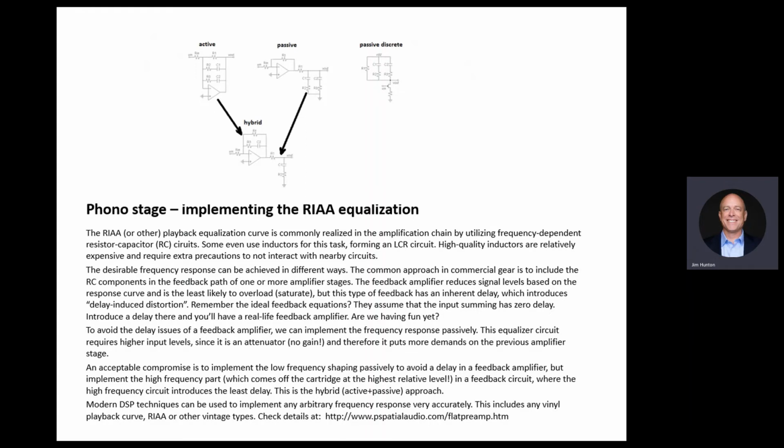I understand what you're saying. The real issue is driving the input circuit. But a lot of times you don't have that problem. I mean, you have 47K, you're fine, right? With a 47K series resistor, the noise floor becomes that of the resistor. That's what most people think. But the 47K is there if you don't have a cartridge.